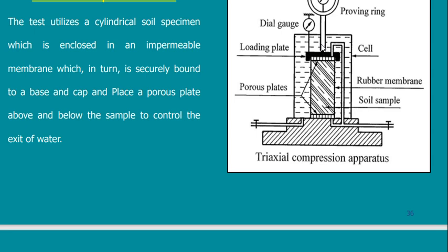For the first case, with a small value of sigma 3, I got a failure of say 10. If I increase the confining pressure, which is sigma 3, would this 10 increase or decrease? Increase or decrease? You said decrease, but you said decrease because this is the normal logic of thinking, that when I add the load, the sample will fail.